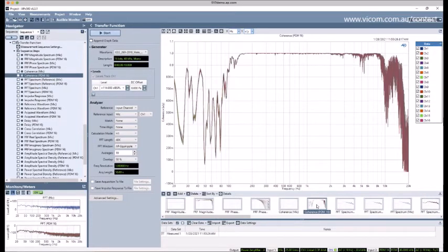In particular, it doesn't have energy at very low frequency, and it doesn't have energy at very high frequency. So in this range, starting at maybe 150 Hertz, all the way to between 8 and 10 kilohertz, that's where I have strong coherence. That's where there was energy in the signal at the relevant frequency. And that's the range in which my measurement results are valid. And so that's definitely something to be aware of when doing transfer function.